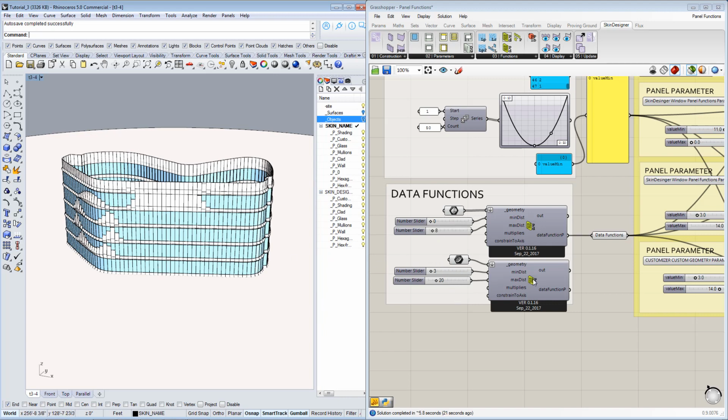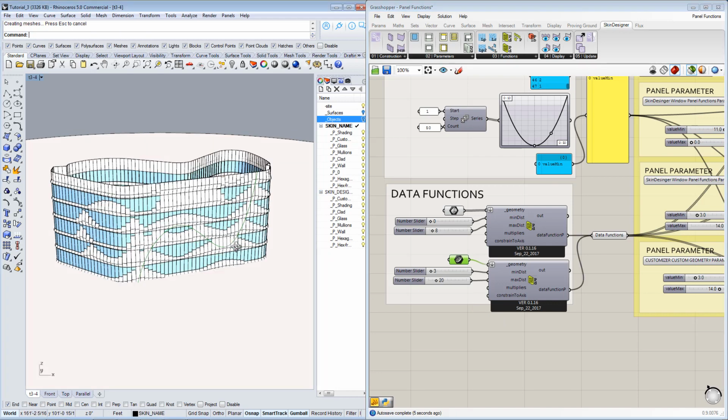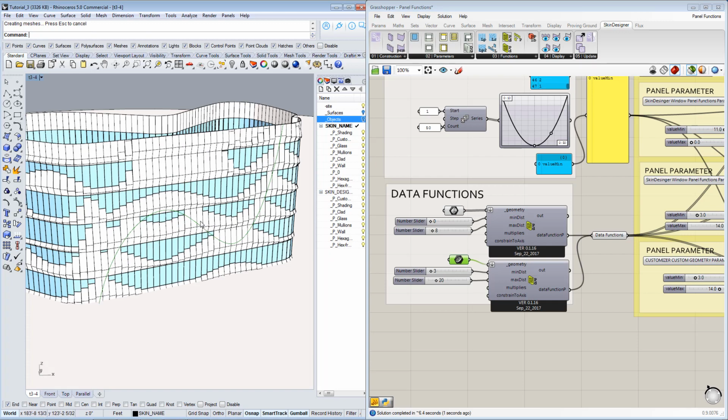Here also I have this curve that I was mentioning, and I can use a curve, not only solids, for these to affect the panel. So in this case I'll give it more range because it's only a thin element, so you need more range probably to have more effect, and this is the distance to the center of each panel that has to be between those two numbers.